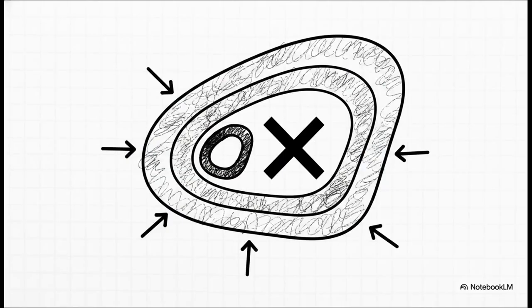There's a really brilliant analogy for this. Imagine the Nyquist plot expanding like a balloon as we increase that variable gain, K. Gain K is just a multiplying factor. If you crank up the gain in a simulation, like in MATLAB or Simulink, the actual shape of your Nyquist contour doesn't change, but the size does. It inflates. If you decrease K, it shrinks. Your system crosses that mathematical boundary from stable to unstable the exact millisecond that inflating balloon expands enough to swallow up our critical -1 + j0 point.